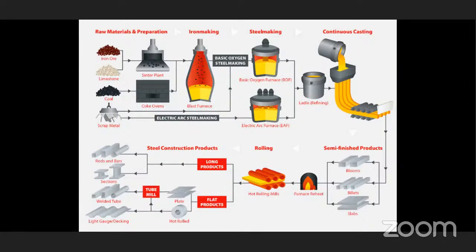So if the pig iron we are using is low in sulfur and phosphorus, then we go for the acid process. This process uses slag that is required to retain only the silica and manganese oxide. Hence the furnace lining that will be in contact with the slag is made of acid refractory material. By this we produce steel by acid steel making.